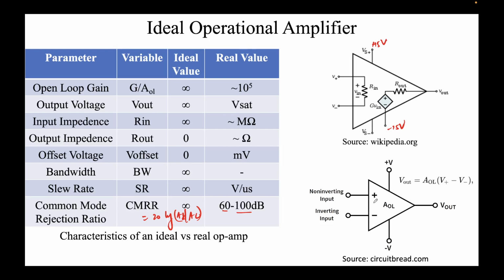You can see the two inputs, V plus and V minus. This plus input is also known as the non-inverting input, because whatever input is provided, the output is in phase. So we saw in the previous 2-3 classes that was always the case. Similarly, if you provide an input to this terminal, the output voltage will be out of phase with the input voltage. You can see this also with this formula, right? So these are some nomenclatures. It's good to just keep them in mind.